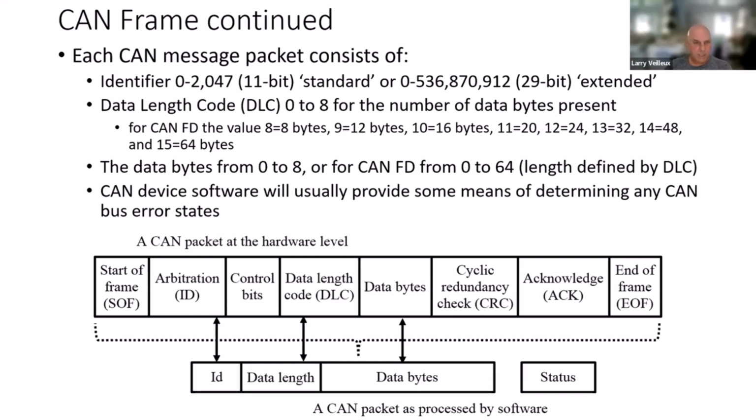the number of ECUs that you'll have on any one CAN bus, but again, a vehicle will have multiple CAN buses, but multiple functions may need more than one ID, even from the same node or same ECU. So there was a need to extend that field. And then if we, let's see, arbitrate, and I'll talk more about how that arbitration ID is used to determine who gets to keep sending. If two nodes try to send simultaneously, well, who wins?